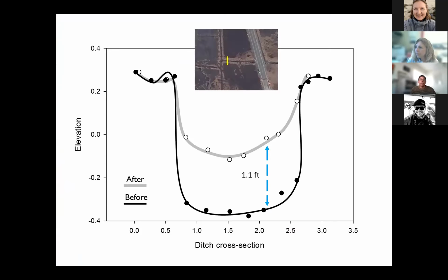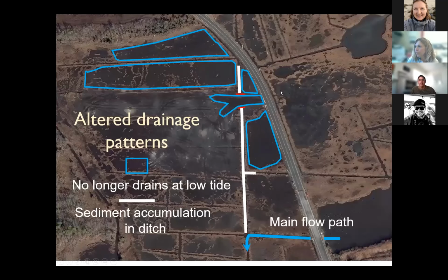It's interesting because when you add material to this site, it actually changes the amount of water volume that the site can hold. So adding material is a way to manage that water balance. You need smaller culverts if you have more material in the site because you're allowing less water in. I don't know if that makes sense, but what I'm saying is these altered drainage patterns may not necessarily be a bad thing in the long run.